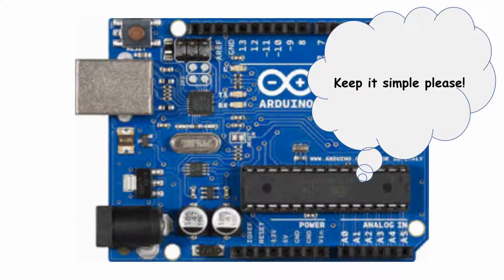Let's do this. When programming the Arduino, or anything else, it is possible to write some pretty complex instructions and get the Arduino to do some really cool things. The problem is that a microcontroller, like the ATmega328 on the Uno, can only execute simple, low-level instructions. These simple instructions include things like add variable A to variable B, or take variable B and put it in register X. And to complicate matters, microcontrollers only speak in binary. For those who don't know, binary numbers are long strings of ones and zeros. Maybe we'll talk more about binary numbers another time.